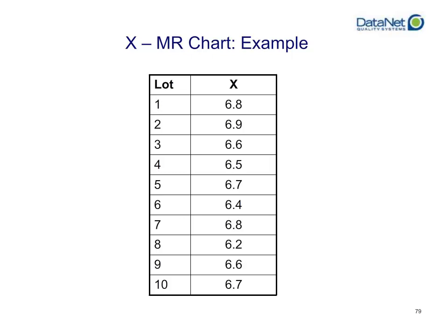You may notice you have a lot less data than you had for the radio example with the Xbar and R chart. And what that is going to do in practice is that you're going to lose some sensitivity to your process changing. You're actually less likely to catch when your process is shifting because you are not plotting an average of a subgroup, but you're going to capture a lot more noise and your control limits are going to reflect this.